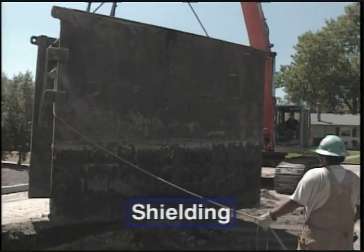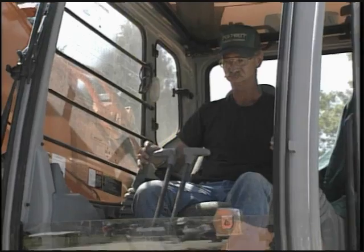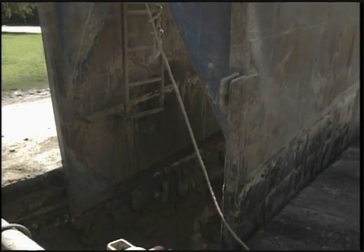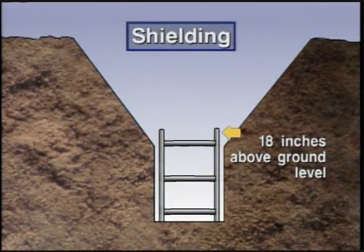Shielding involves the use of a steel box that is open at the top, bottom, and ends. As the work progresses, the box is pushed or pulled along the trench to protect workers in the event a cave-in occurs. The shield should extend 18 inches above ground level.